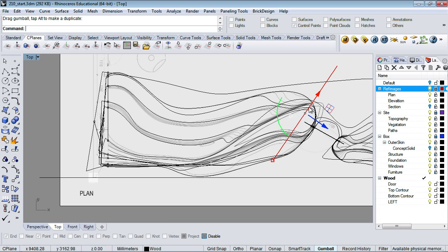Yeah, exactly. And so as I do this one, then I would rotate again, because the door is the next critical point, because this is where we want a straight surface for the door to align to. Now that I know where the door is, I would be a little bit more careful about getting it parallel to the door frame. Then I would draw this curve and the start of this curve over here on the same plane. That way I have snapping points when I want to add the next geometry. I have a group of geometry there that I can snap to. Okay?